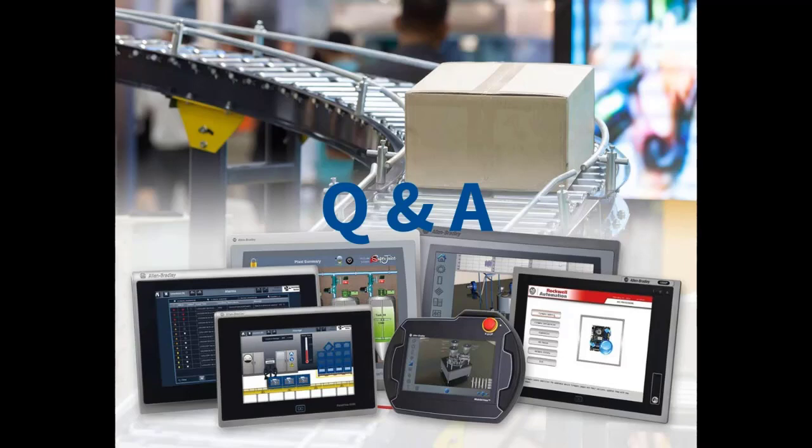During that installation, you would choose which version of ME Station you download from Rockwell and then install onto the terminal itself. So if you wanted the latest and greatest, you would download FactoryTalk View ME Station 12.0 and install that on the computer. And that would essentially be the firmware, or MER required versions, for that particular terminal and computer.